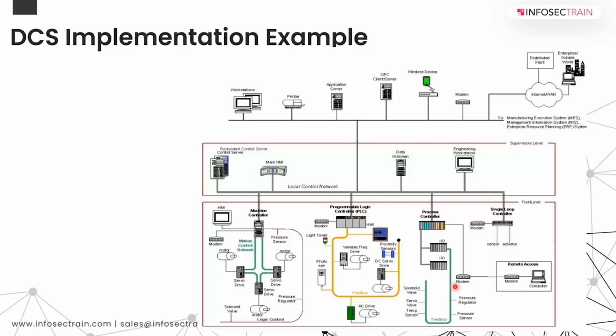And sometimes there is also a PLC available for various reasons, that controls smaller processes instead of burdening everything on the DCS. It's a combination of DCS, distributed controllers, plus PLCs for certain process applications. Again, these are purely application dependent.